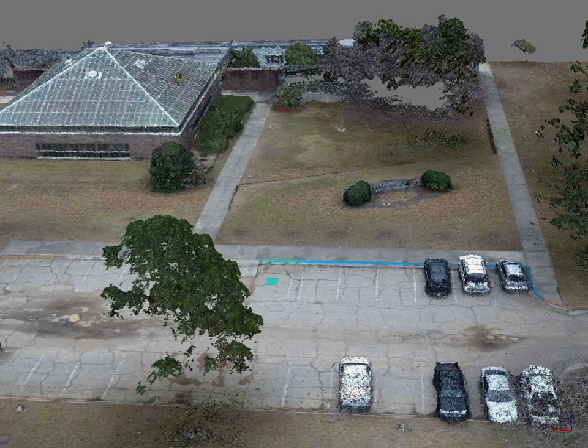If you do not put down ground control, your point cloud will still be relatively extremely accurate, right? From the ground to the top of the tree, it's very accurate. But if you bring that data into your GIS, the whole thing might be shifted spatially 3 or 4 feet. So to get that absolute geographic accuracy, you can bring in ground control and produce better results geographically. Here, instead of looking at trees, we're looking at Lomax Hall.